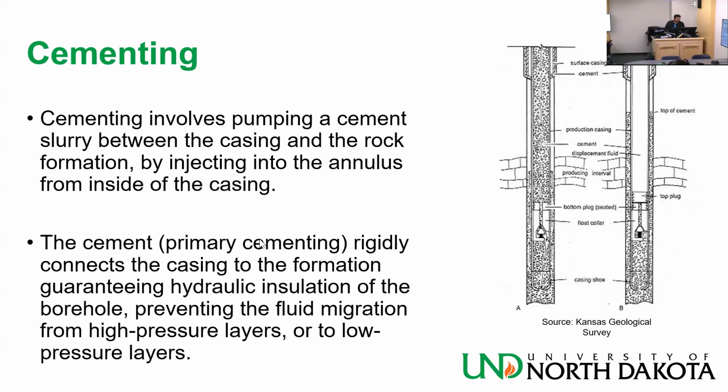Yeah, the cement mixing. The primary cementing rigidly connects the casing to the formation, guaranteeing hydraulic insulation of the borehole, preventing the fluid migration from high pressure layers to low pressure layers. So primary cementing is basically what you think cementing is. Secondary cementing is to fix anything that went wrong in the primary cementing.